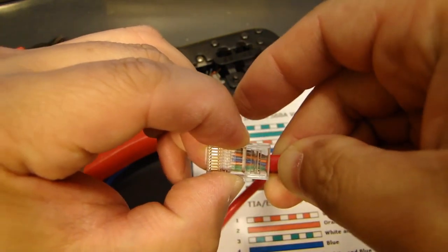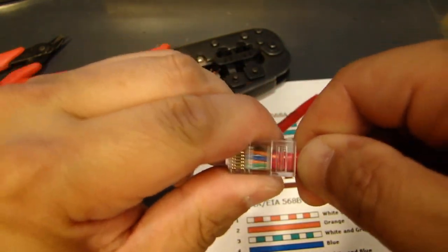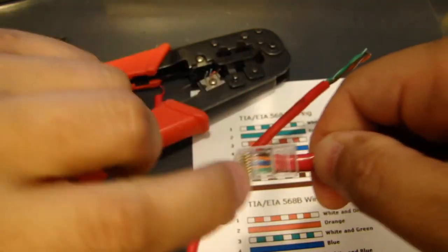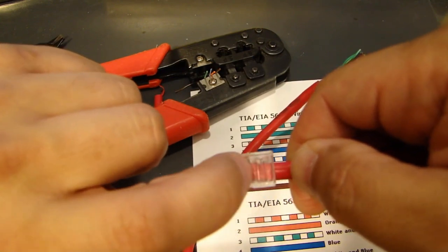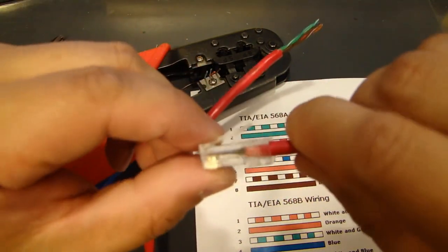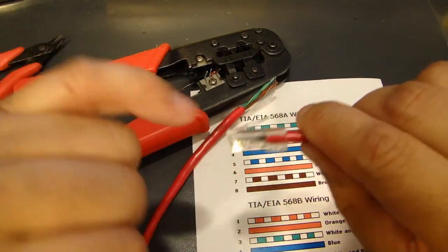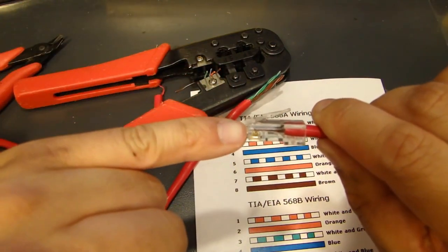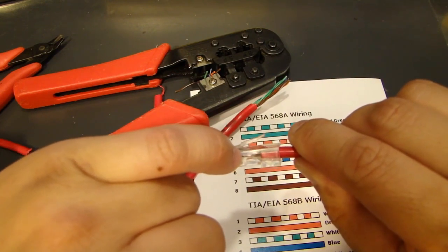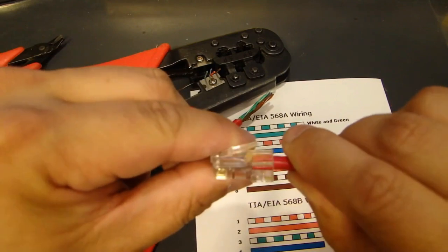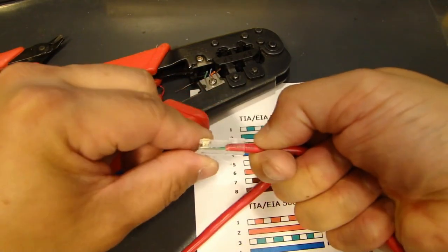And once you get it in there, you'll be able to slide the wire in there until the insulated jacket is in this part of the connector. Okay. The next thing you want to do is look on the side, make sure the wire is fed all the way to the end. If it's not all the way to the end, let's say you cut it too short, it's back over here, you need to start all over. Okay, so these wires are all fed in there.